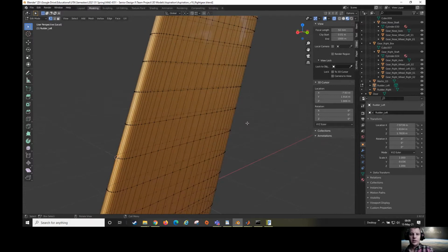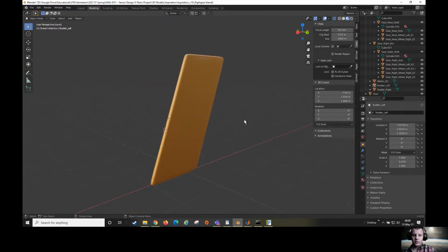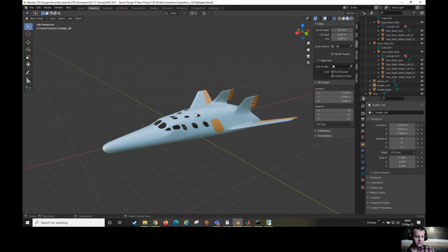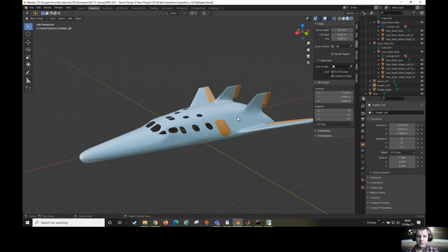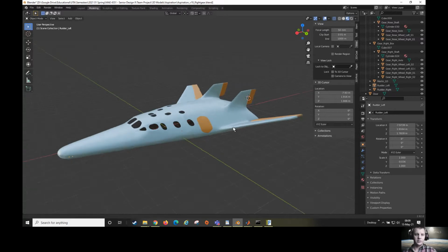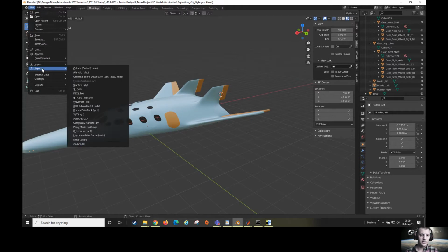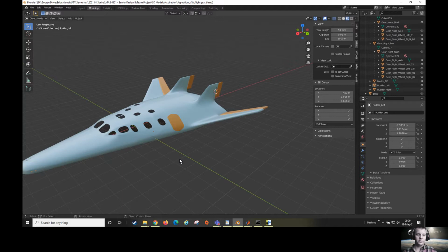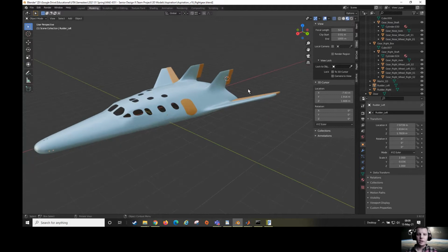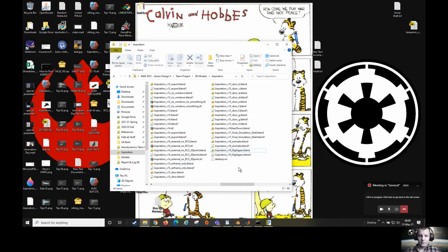So that's everything in Blender that is kind of imperative to get a model working. Is one, you need this add-on to export. If you don't have that, you can't export a model to Flightgear. And 2, setting the origins and finding the locations of points around which you want to pivot. Okay, so that covers exporting and animations.